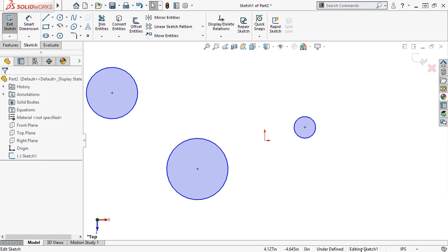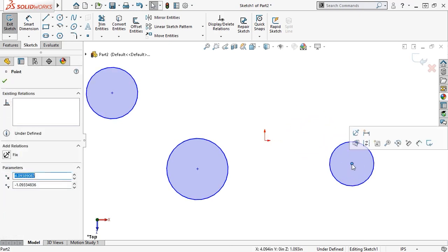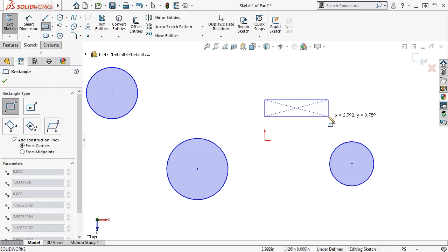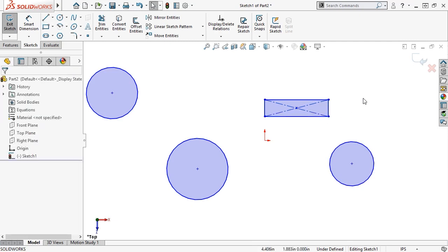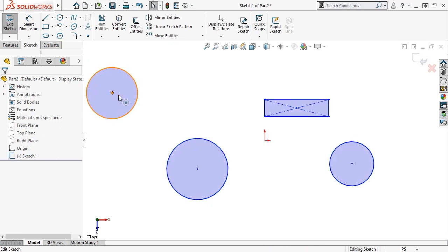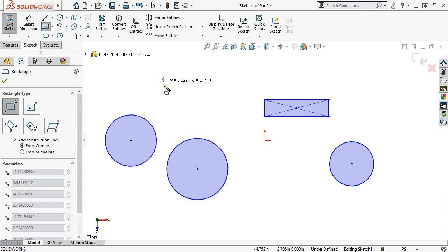Notice that I'm now editing sketch 1, and the familiar sketch icons appear once more. At this point, I can modify the geometry or move it. And I can even add additional geometry if I wanted to. If I press the D key to bring confirmation corner to my cursor and select the Exit Sketch button once more, I'm back in Editing Part mode. I'll click again on the sketch and select Edit Sketch. I'll make a couple changes here. And I'll sketch one more rectangle.